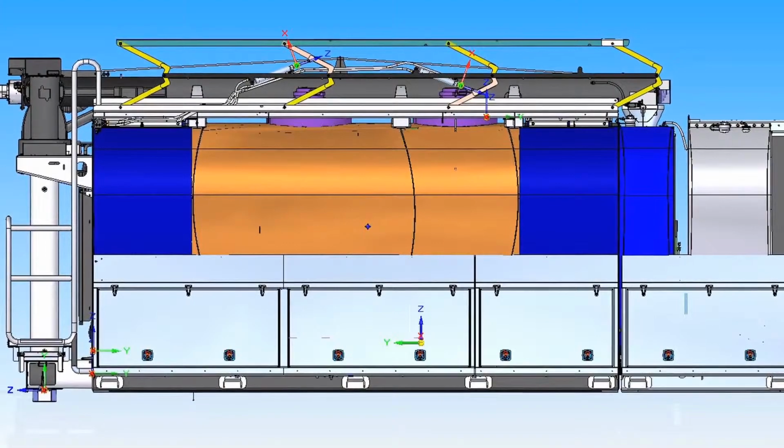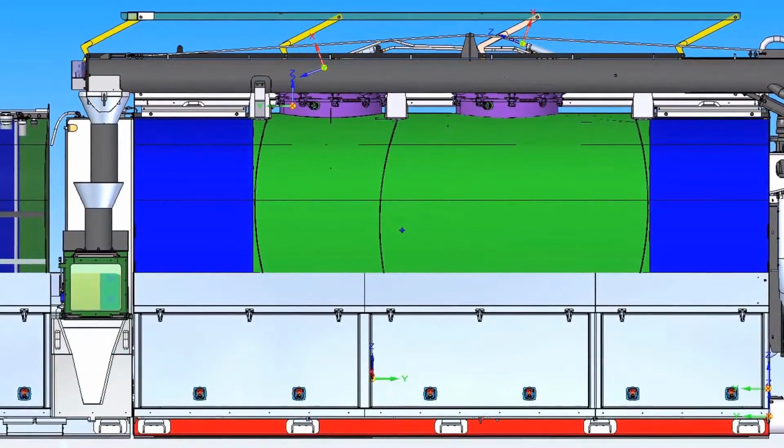A lot of our vendors will have CAD drawings on the shelf of some of their components, and they'll send it to you, you download it, boom, you open it up in Solid Edge and save it as a PAR file, put our part number on it, and we've got it. We don't have to redraw it again, but sometimes the customer drawings are not 100% perfect for what we need. They might send us a model of a hydraulic cylinder in its retracted position, and we need a model of it in its extended position, and synchronous makes that very easy. So we can take their model, change it, put it where we need it, and we're done. And that probably cuts time on a part like that down by a factor of 10.